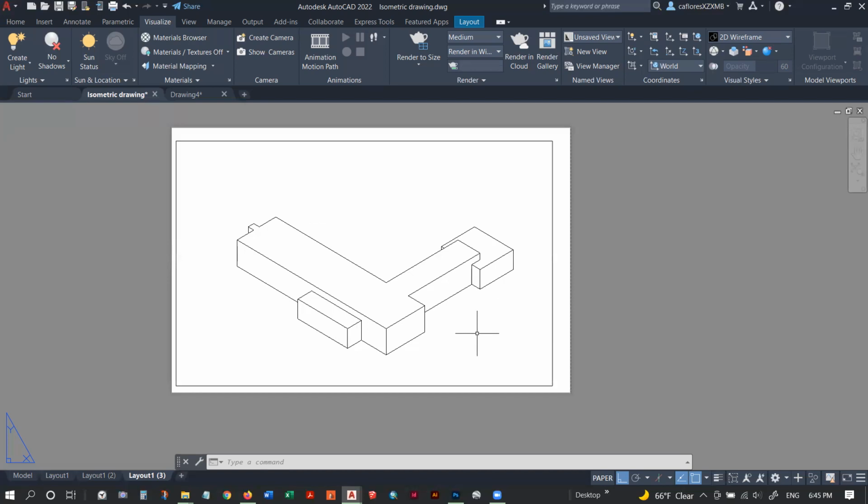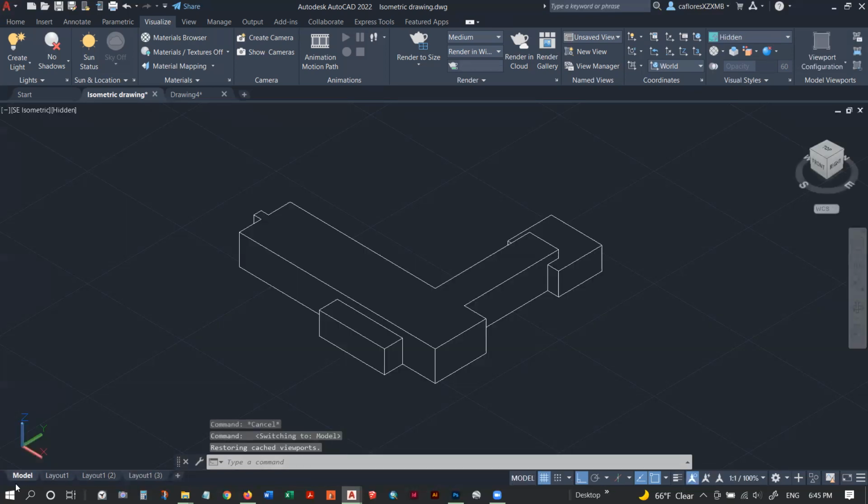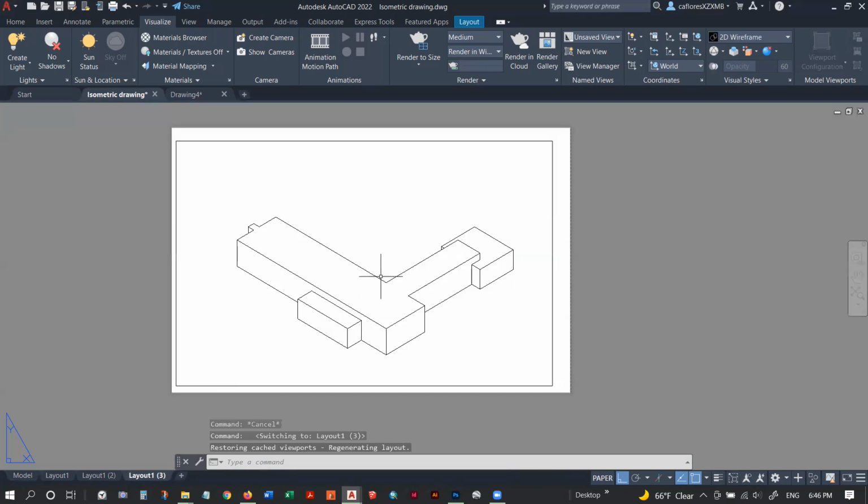The really complicated way that I tried to explain in class this morning was because I knew it was going to shrink to 82% of the original. What I tried to do in class was I enlarged this one by the same factor that I knew was going to shrink when I changed to isometric view. And it's really complicated and it's easy to get the math wrong. And even if you do everything right, you're going to have a little bit of rounding error, so it's never going to be quite the same. For that reason,